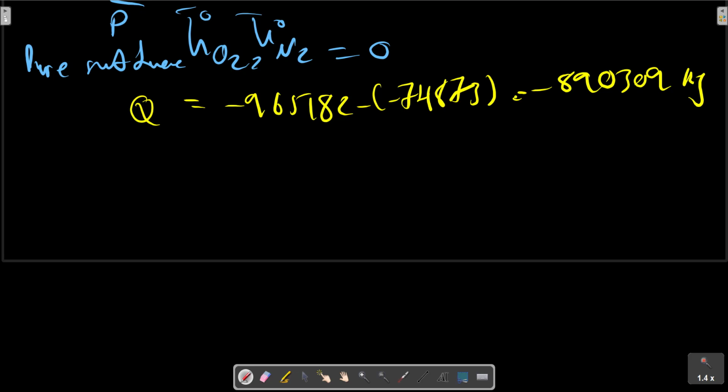In most instances, however, the substances that comprise the reactant and product in a chemical reaction are not at a temperature of 25 degrees centigrade and a pressure of 1/10 megapascal. Therefore, the change of enthalpy between 25 degrees centigrade and 1/10 megapascal and the given state must be known. For a solid or liquid, this change of enthalpy can usually be found from a table of thermodynamic properties or from specific heat data.